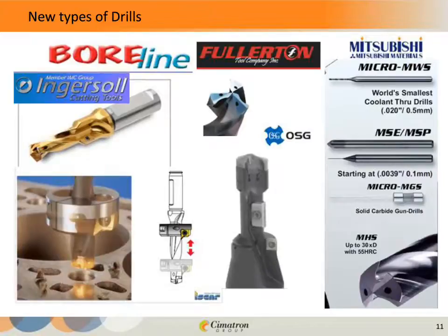Up here at the top, there's some 3-flute tools that I found from Fullerton and OSG. There's some really nice advantages to 3-flute drills. One thing is that it's able to be more self-centering because of it being 3-fluted. It tends to not work harden as much, and of course you can feed it quicker because you've got 3 teeth doing the work. And later on we're going to look at a video of that tool in action.